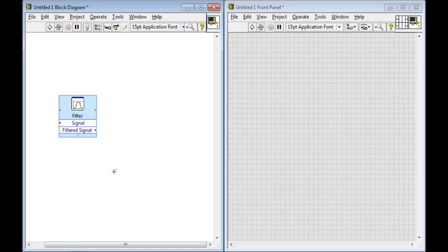What you're going to do is use those two formula blocks that you saw, and I'm going to show you how to use them right now. You're going to implement the formula to convert voltage to strain and then strain to Young's modulus. We want you to calculate Young's modulus in LabVIEW right away so that you know if you're getting the proper data or not. This lab is very, very, very hard to get good data. So that's why we want you to calculate everything right away so you know if you got proper data or not.